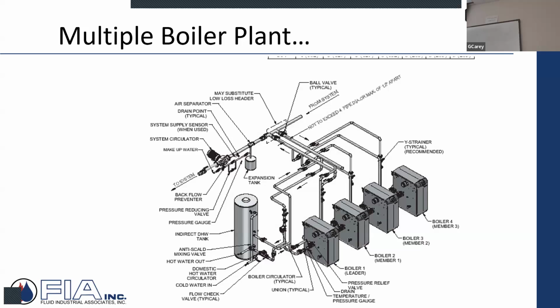And the one scenario that could happen that you don't want to have happen is when, in this case here for heating, the flow here is greater than the flow here. Because now if I'm over pumping here, some of my hot water is going to go what? It's going to go backwards and it's going to elevate my return temperature. And the problem with that would just be if I've got this high efficiency condensing plant and I'm elevating my inlet temperature, I'm reducing my efficiency. So there wants to be some intelligence back here to try to prevent that from happening. Maybe variable speed pumps on the boilers, and they'd start to ramp down.